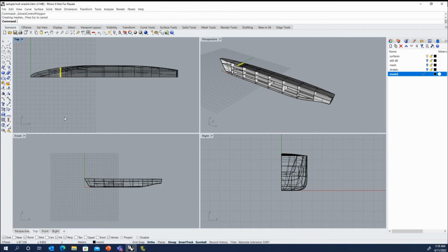Now, this is if we use the script version, and the script also requires a uniform spacing. You can see we only had a single spacing available there. So it went from the center line all the way to the outer shell on 1 meter increments. There's no option to do 1 meter for the first 5 and then change the spacing.